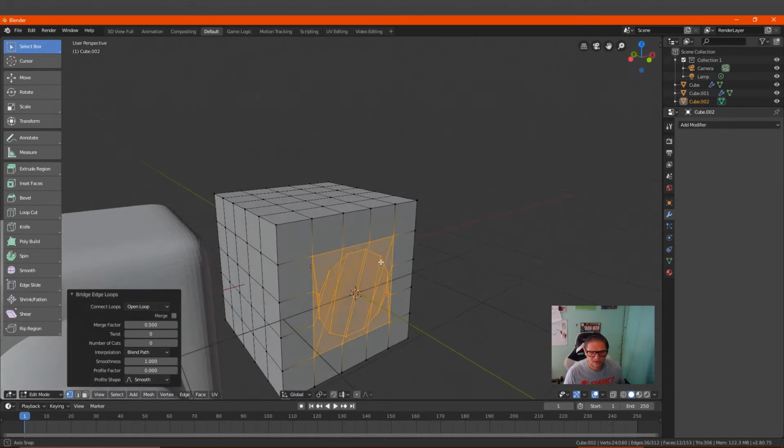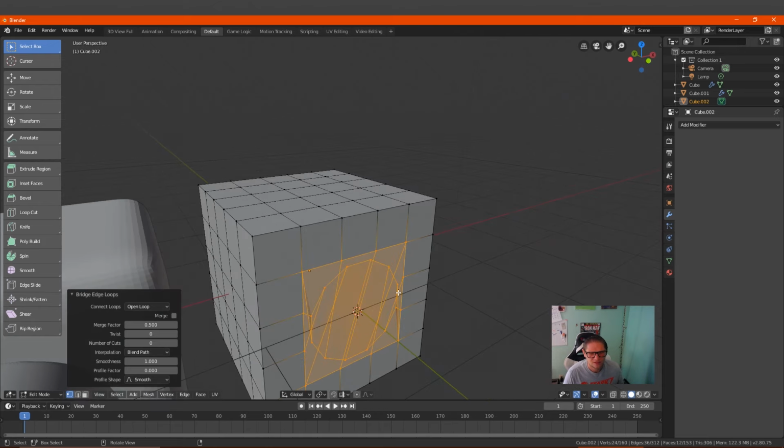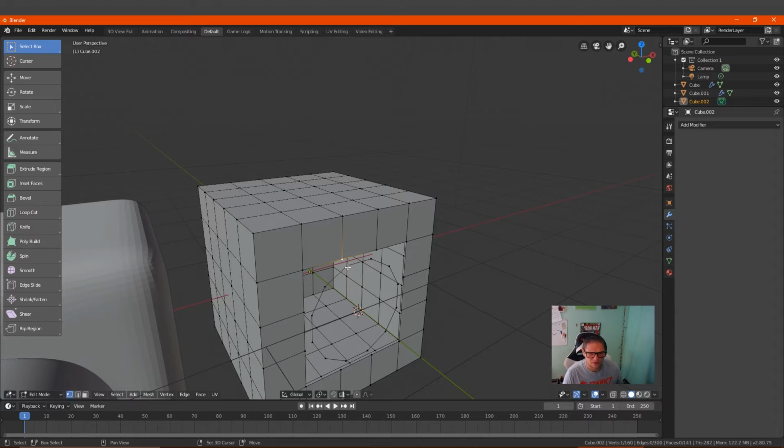And that's going to go ahead and, ooh, that was messy. Okay, sometimes it's a little bit messy, so we're going to Control Z that, and we're just going to individually face these off. So we're going to click that one and that one. We're going to hit F, and we're going to face each one of these off. If we keep hitting F, it should go all the way around the circle.